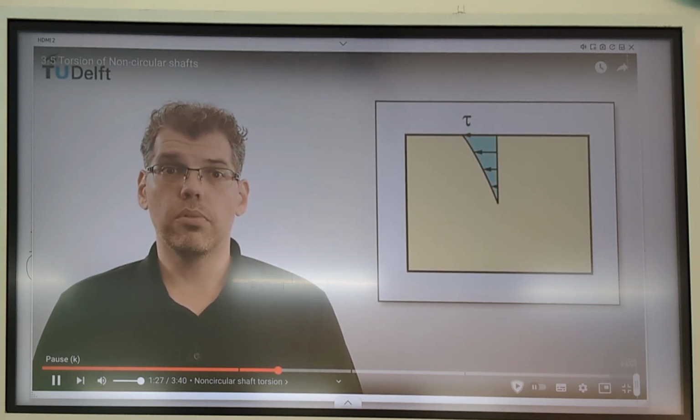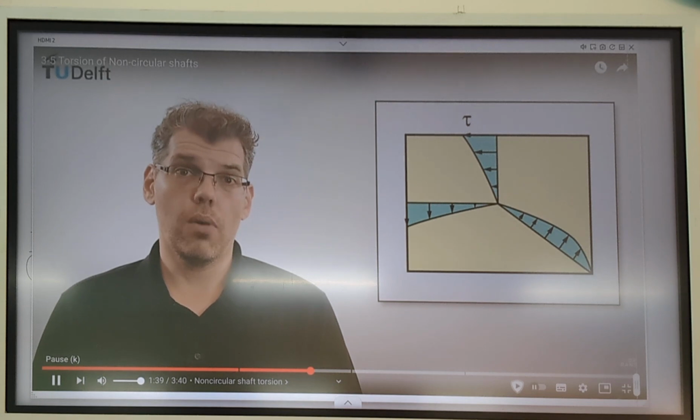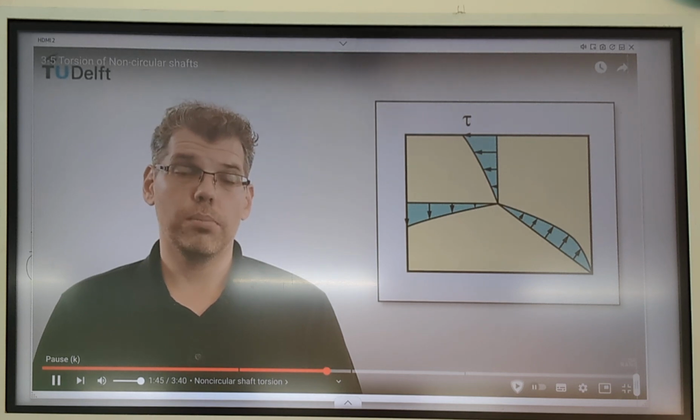As we sweep through various angular positions, the fluid flow, or the stress flow, around that cross-section will warp and change to maintain the same resultant flow around that cross-section. Thus, for non-circular cross-sections with this variable geometry, we'll have a very complex stress state as illustrated here on the rectangular cross-section.